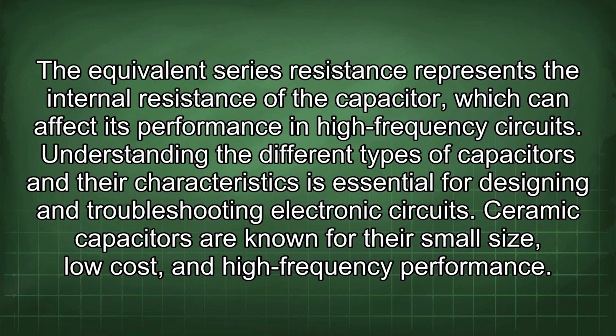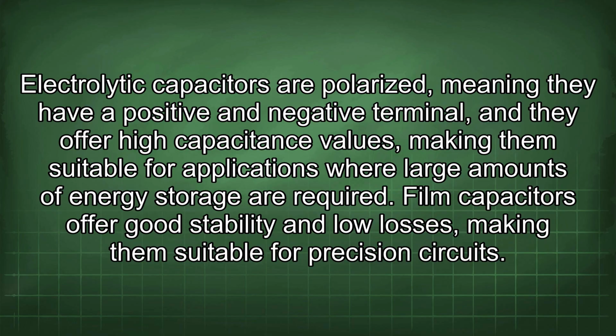Understanding the different types of capacitors and their characteristics is essential for designing and troubleshooting electronic circuits. Ceramic capacitors are known for their small size, low cost, and high-frequency performance. Electrolytic capacitors are polarized, meaning they have a positive and negative terminal, and they offer high capacitance values, making them suitable for applications where large amounts of energy storage are required.